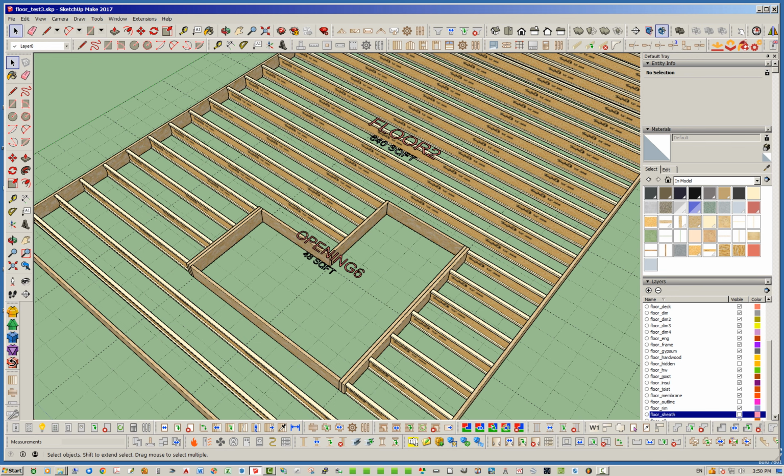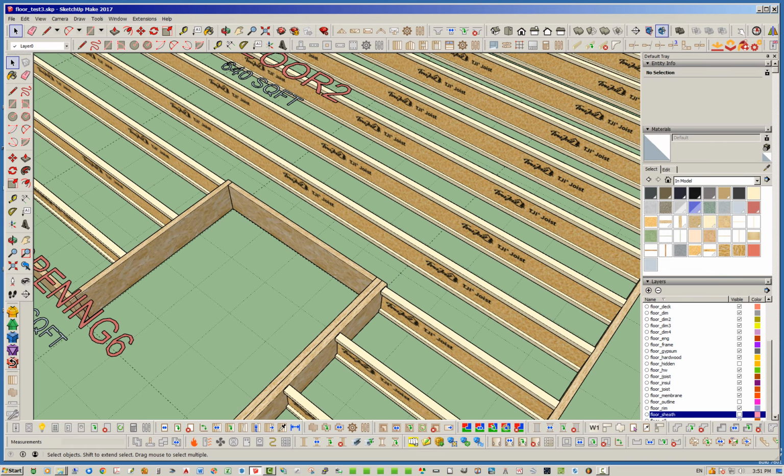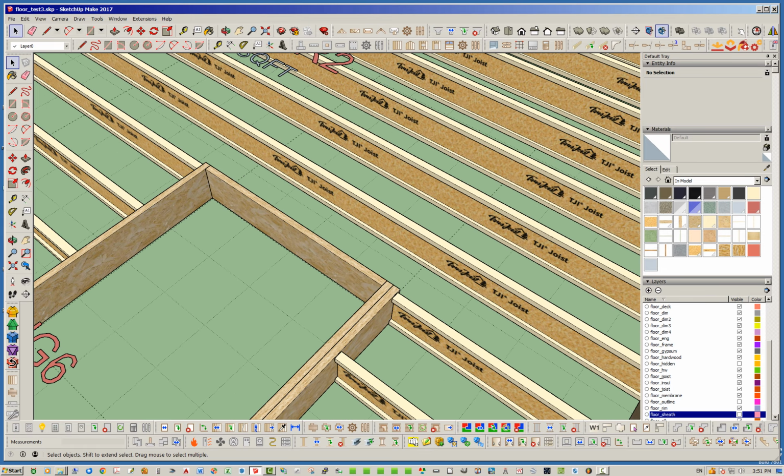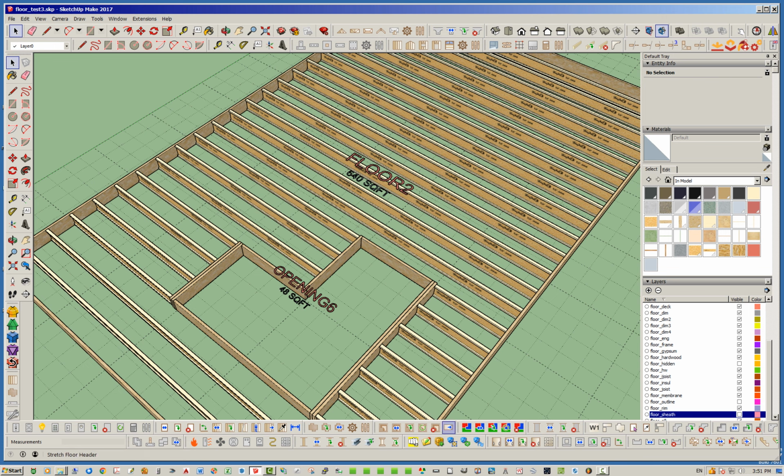So now this is where it gets interesting. Before, to bring these headers over to the joist, you had to manually edit, go into the menu and basically key in those numbers, which is time consuming, and you've got to go back and forth between the measure tool and your edit menu and all that. So now it should be a little easier.